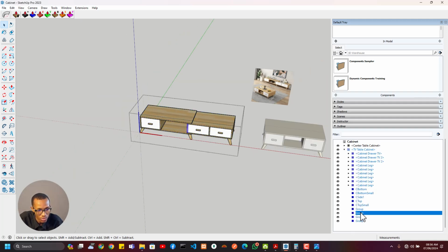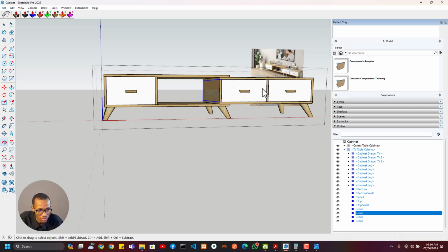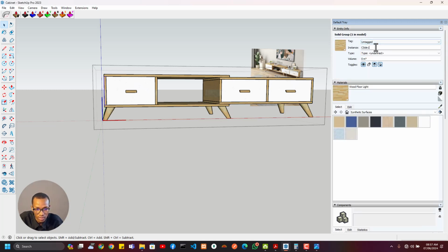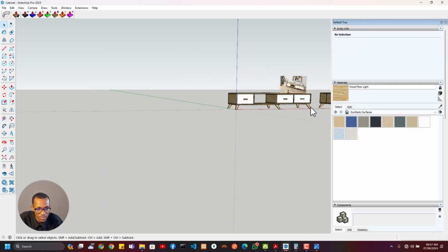So there are some ungrouped elements there, but you can decide to name them. But most of the times, remember my reasons for grouping. All right, so this is side one. So I'll just go ahead and give the other sides then label. All right, so you know my reasons for grouping. Grouping is very important. It enables you to navigate around your model so that you can easily turn off different parts or different components of your model, which is very important.